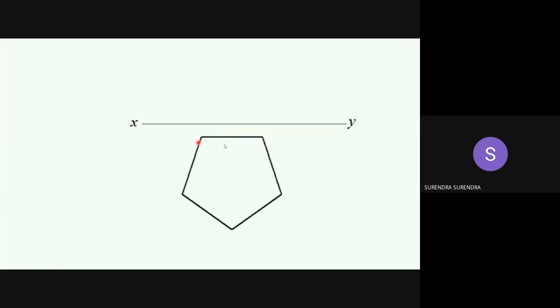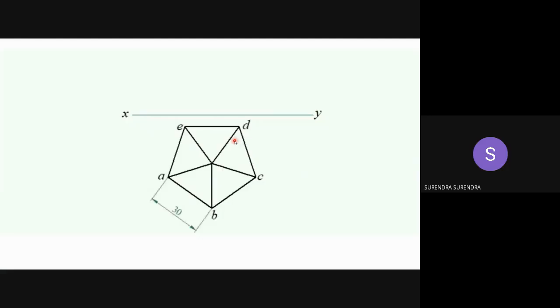So you must draw in top view a pentagon with an edge of the base parallel to VP. As it is a pyramid, join all the base corners to the apex. In top view you can see all the 5 triangular faces. So you must draw these lines with HB and complete the dimensioning also.